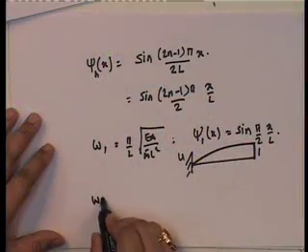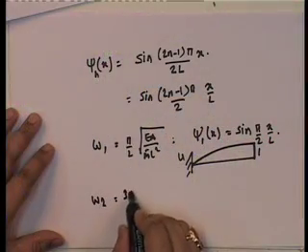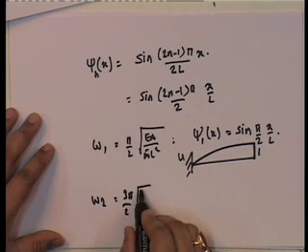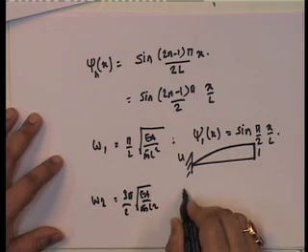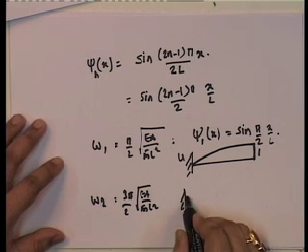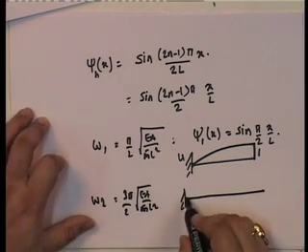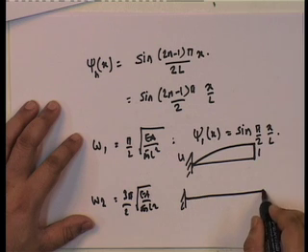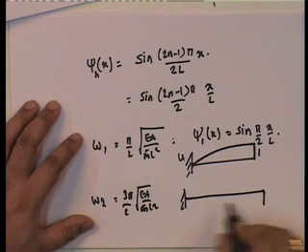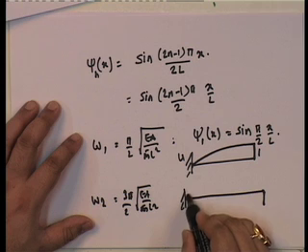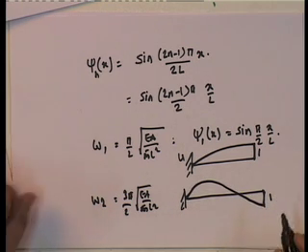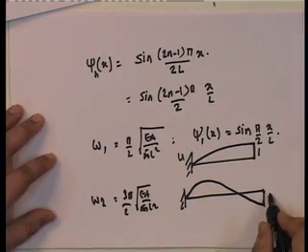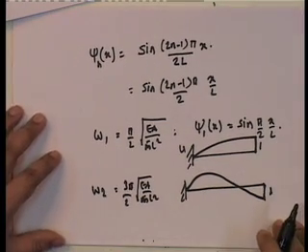Okay. So, omega 2 is equal to 3 pi by 2 root E A upon m bar L squared, and the corresponding mode shape is sin 3 pi x by 2L. So, therefore, it is going to be in this way, going to 1. Okay, because at 3 pi by 2 it's minus 1. Okay, so that's how I'm going to plot it.